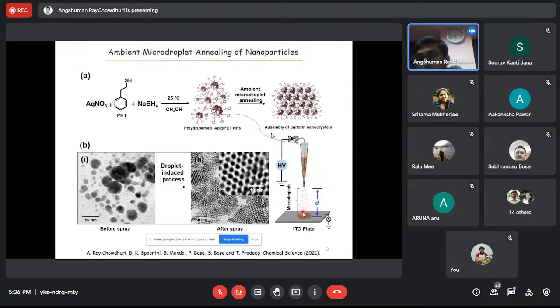If it is less, then the droplet size will be different. Another one is the potential we are applying. So we have to play with the potential we are giving to the platinum wire electrode, the tip to collector distance, and again the solvent in which the material is dissolved. That is also a parameter.